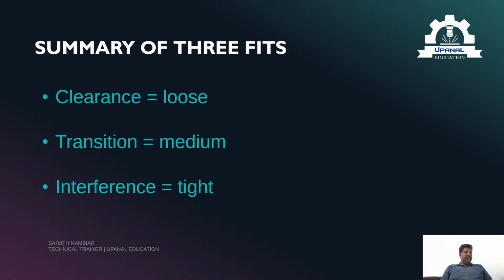Compare it to a handshake: clearance fit means just a loose handshake, transition fit will be a firm handshake, and interference fit will be a tight grip. Think of it like this and you can always remember: clearance is loose, transition is medium, interference is tight.